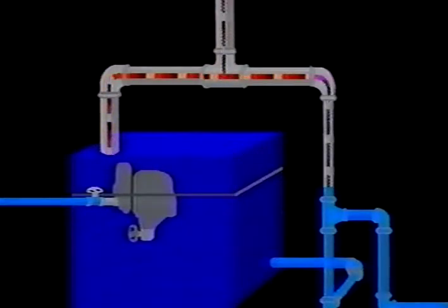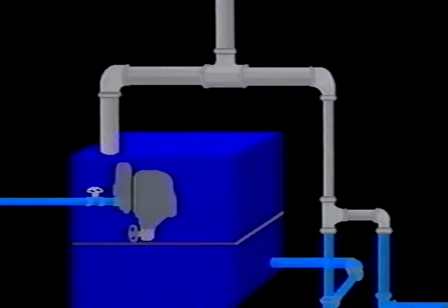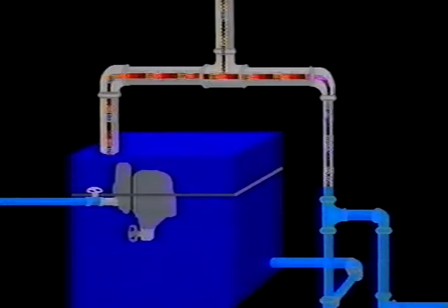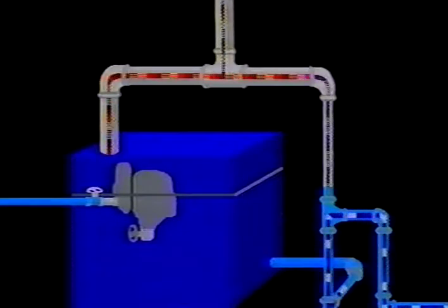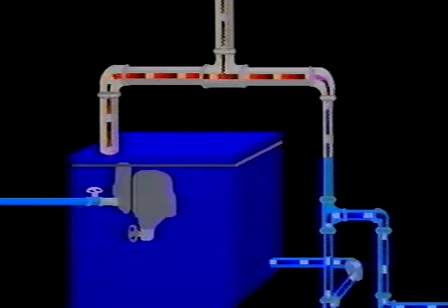It is never a good idea to use a water feeder to increase steaming time. On these installations, fresh makeup water is introduced into the system every time the water feeder is activated. The accumulation of this makeup water will gradually flood the boiler and require frequent manual draining of the boiler to restore the proper water level.